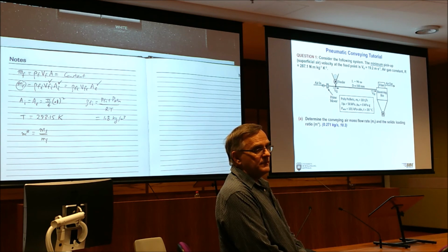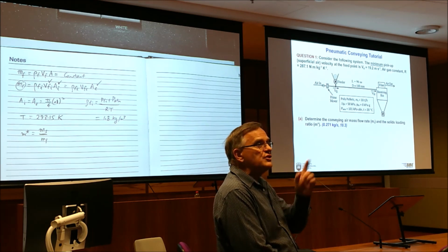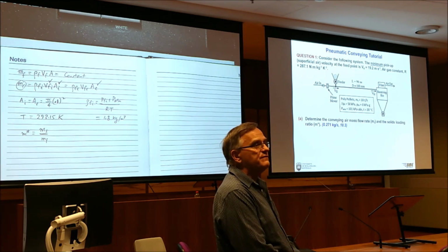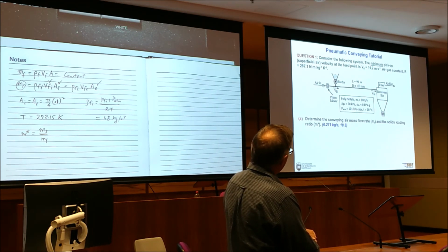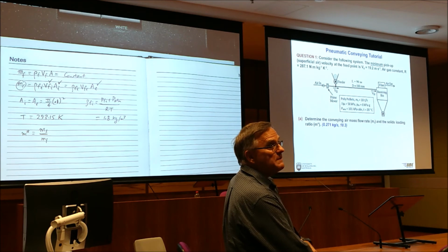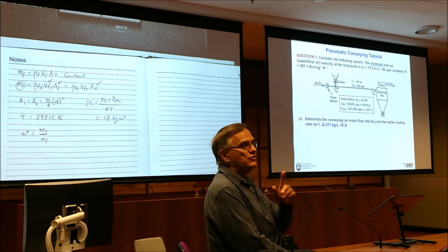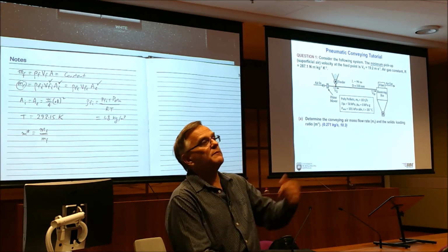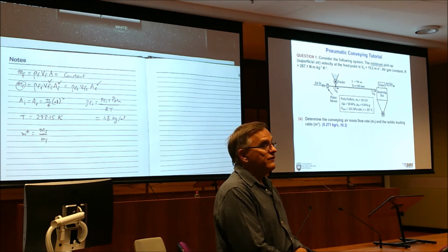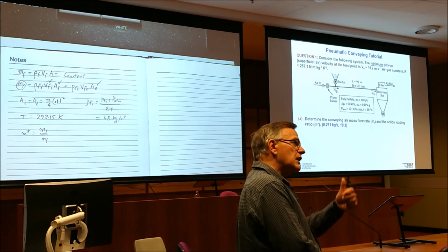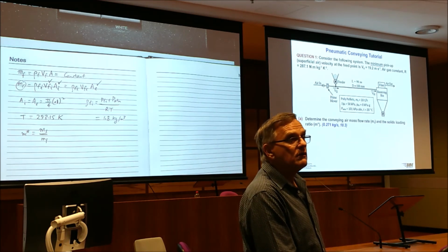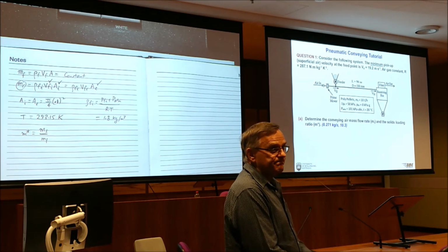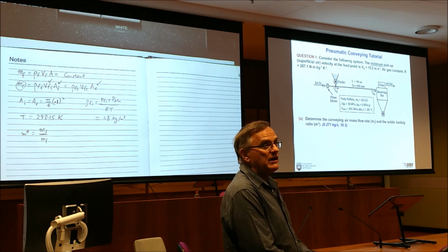Alright, so read the question carefully, check the information carefully. This is a minimum conveying velocity. So this airflow that we calculated, air mass flow rate, is a minimum mass flow of air you need for 10 tonnes per hour of this product through that pipeline. So if we exceed M star, either increasing product flow or decreasing airflow or both, we're going to block the system. We haven't got enough air to sustain the suspension of those particles.